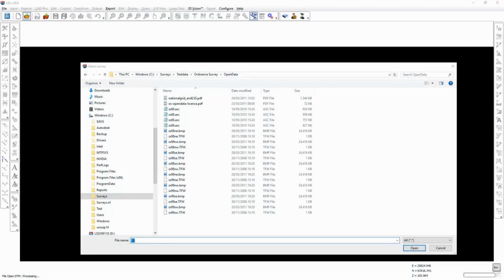Output visibility point feature is the first of the ZVI and ZVT commands I wish to show you, but in order to demonstrate this properly I'd like to go through a straightforward worked exercise which involves importing some off-the-shelf DTM data and also draping onto that some map information, and then we can identify an area where we want to establish some new development, and then we can do some ZVI and ZVT analyses.